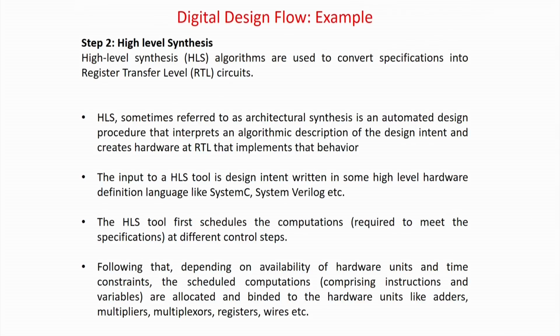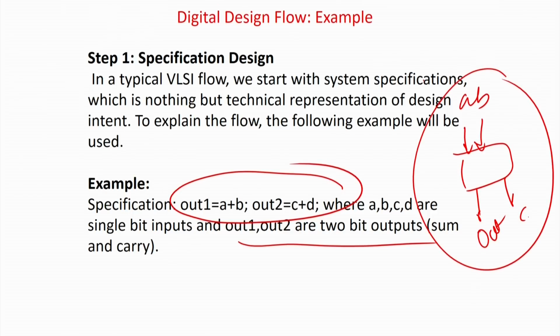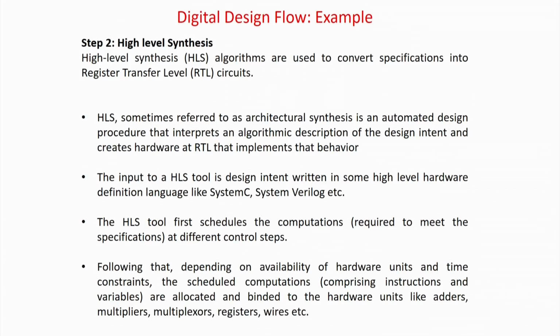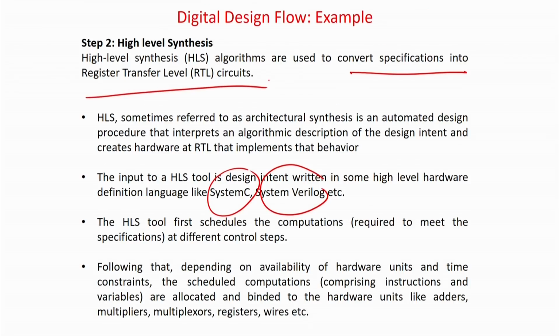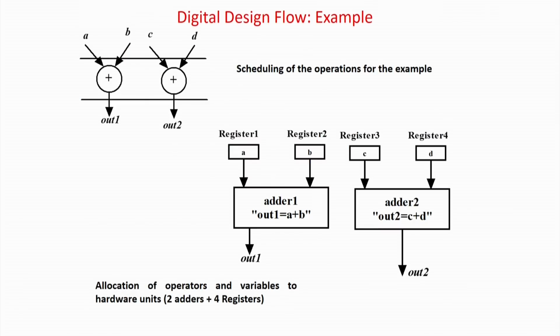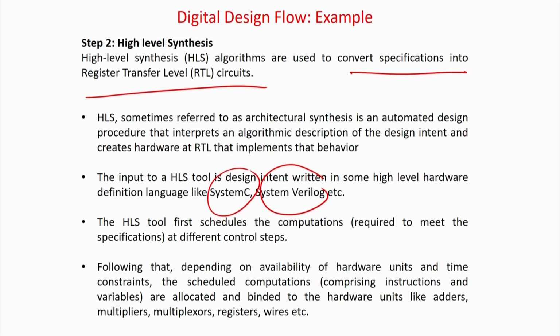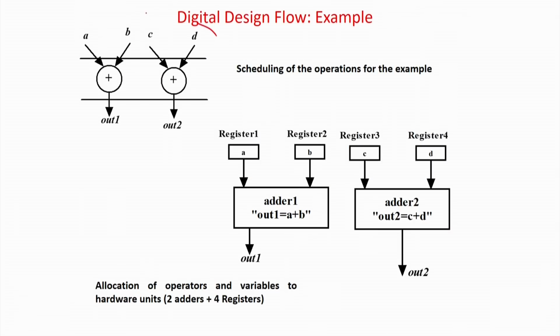In high level synthesis, implementations like block diagrams have to be written in an abstract language, like SystemVerilog or C, some higher level languages, so that the tools convert these block diagram specifications into register transfer level circuits. Register transfer level means you have some registers, some combinational circuits, some registers, and so on. Then the combinational circuits will be synthesized at gate level by automatic tools. Anyway, you can read this slide, but an example will make things more clear. Then we can come back to this slide. Say for example, we require something like this.